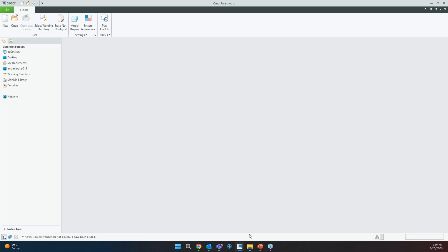This is something which I really find interesting, because sometimes there are a couple of licenses which our customers use, and you have your design, you have your manufacturing, and whenever someone opens up Creo, all these licenses get acquired. Now I don't want that to happen. Whenever I open Creo, I just want my manufacturing license. Say if I'm a manufacturer, I just want my NC manufacturing licenses to be acquired. So I can configure my Creo in such a way that only one license from my floating license gets acquired, and all the other licenses are left free.